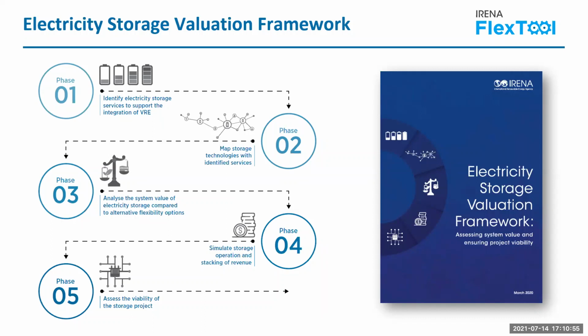we precisely use a capacity expansion model that can be used to capture the value of storage and the respective capacity that would be, or could possibly be, required in your system, compared to all other flexible alternatives. And afterwards, or jointly, we can also use a dispatch model to optimize operation and capture the multiple stacked benefits of storage.